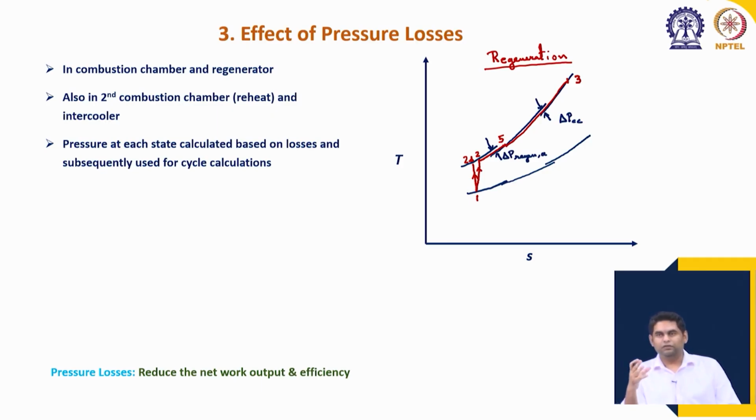So, there are devices which block the flow within the combustion chamber, as we will discuss later, and these are used for creating local pockets. These are known as flame holders. This creates local pockets where the airflow velocity is quite low and the flame can be sustained, and then the combustion can proceed. As a result, these are necessary, but create some pressure loss due to drag.